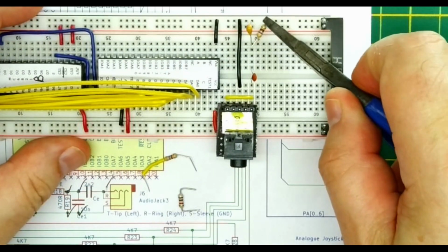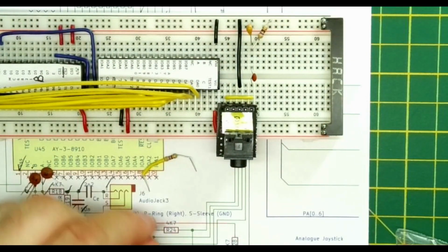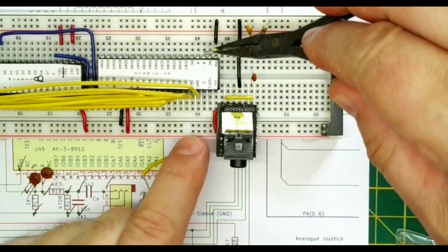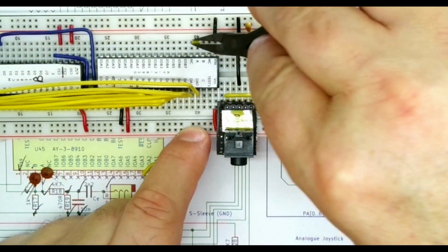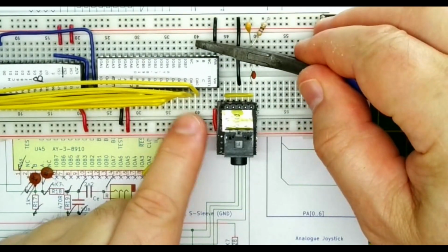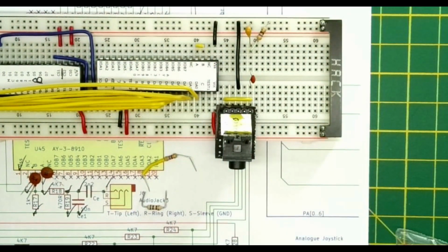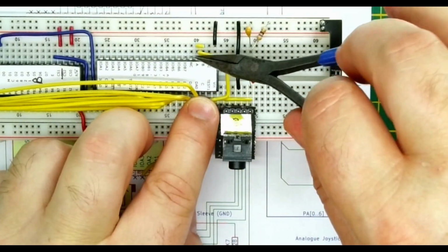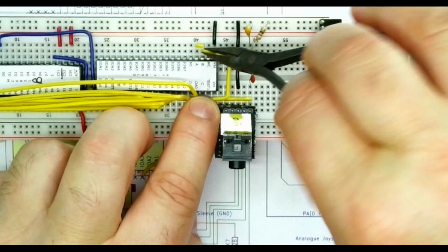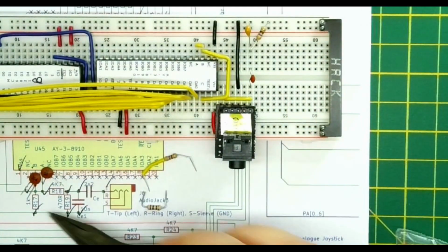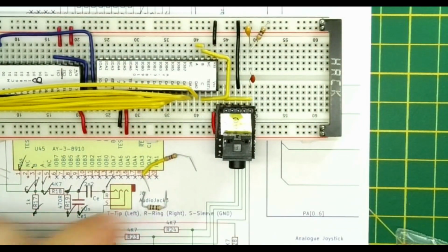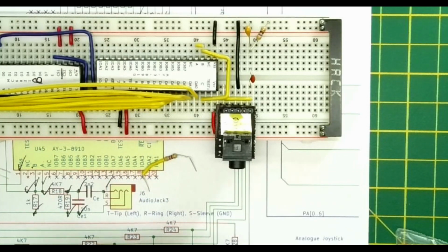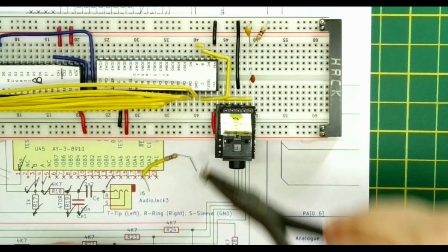It's tied to ground. Then we need to connect the A, B and C together, so I'm just going to wire B and C together there. Okay, and then I've got a wire I've already made to join C round to B. Then we need this 1K resistor going from A, B and C down to ground as well, and that's probably easier to wire that up on this side here.